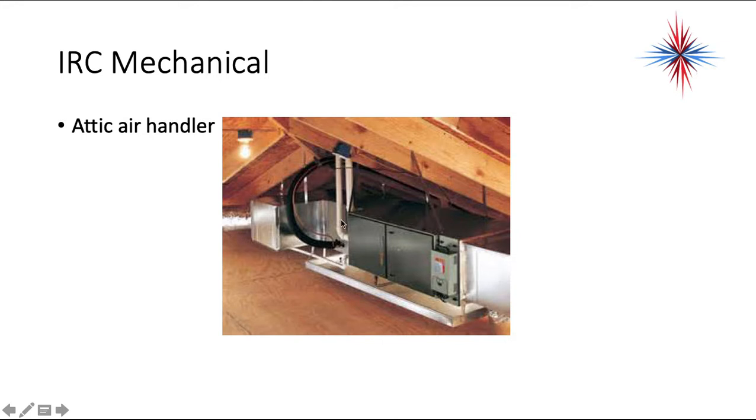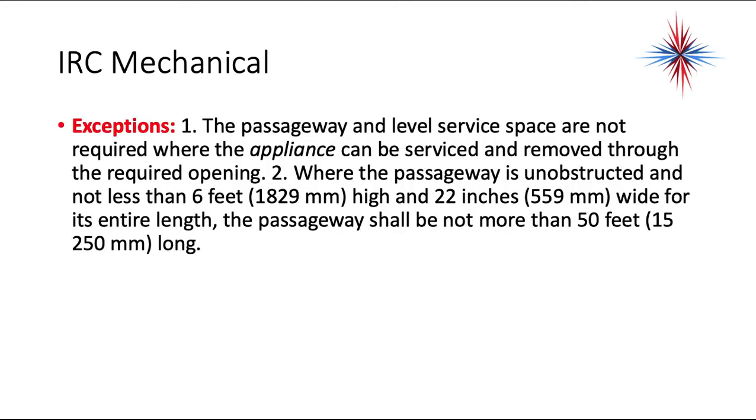The other issue is if this is installed in the northeastern part of the country or areas where attics freeze, you cannot use a condensing furnace, which this is because of the 2 PVC lines. You cannot use a condensing furnace in an attic without heat tape on that condensate line because the water in it will freeze. Again, manufacturer's instructions trump code.